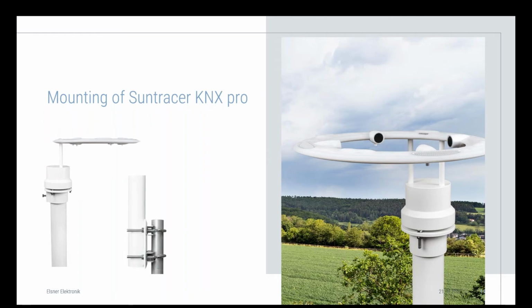Here you can see the assembly with the mast as an extension. The weather station must be oriented so that the base of the device faces north and the ring faces south, as displayed here. Also, here in this picture, I added the north and the south orientation.